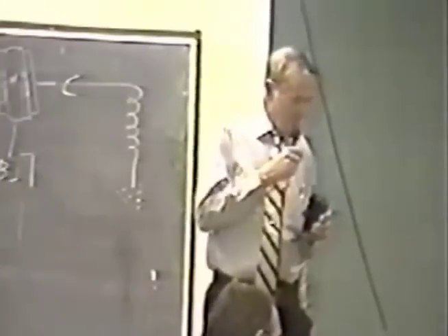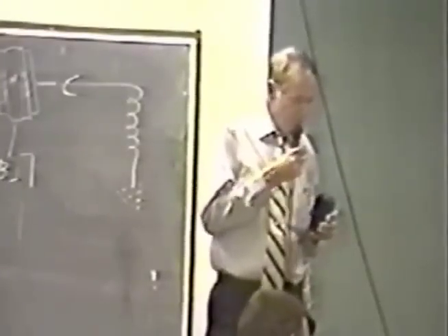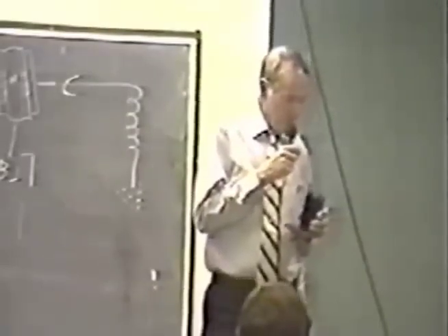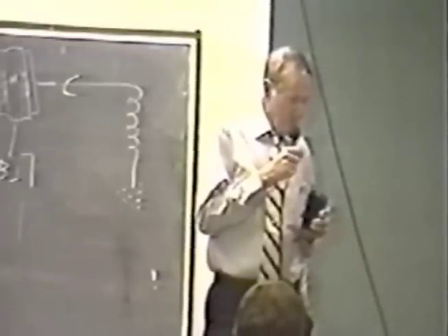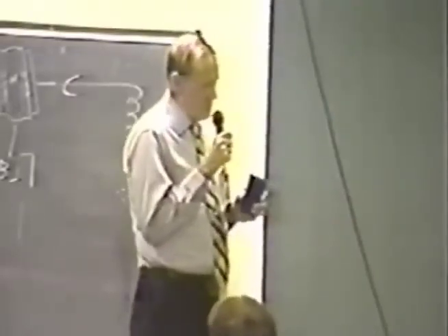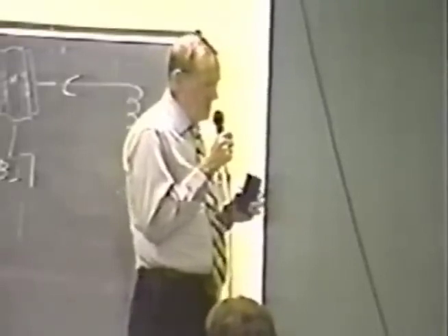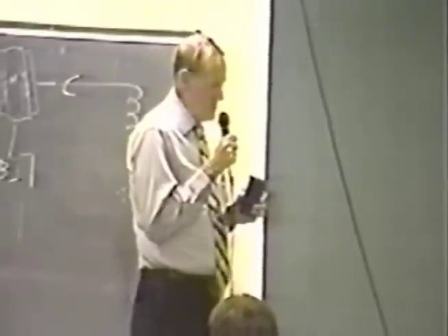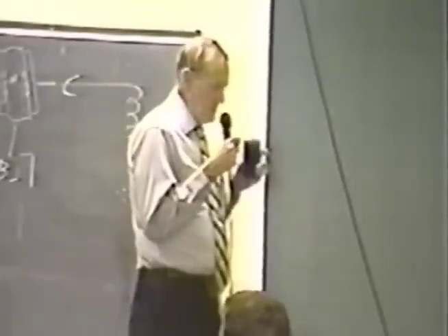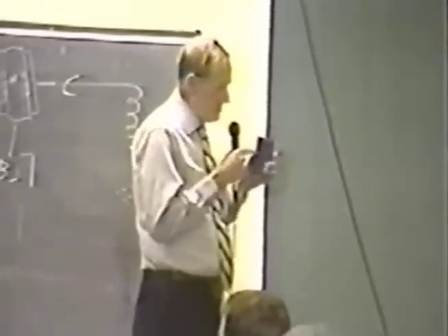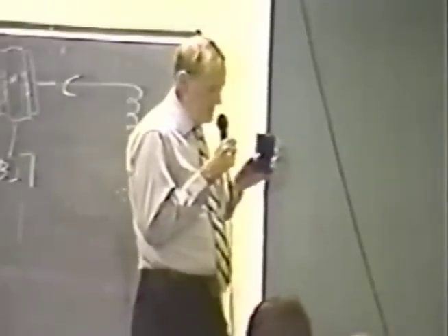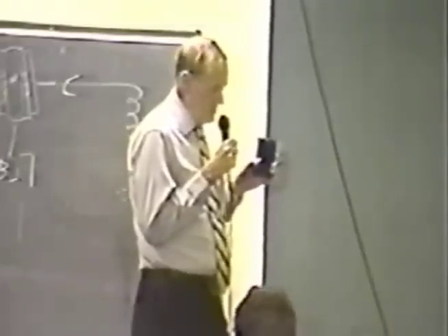You have a question? Okay. What are the possibilities of voice modulating the signal coming out, using it as a transmitting device, receiving communications? Very definite possibility, but one has to have a detector in order to demodulate, in order to use it as a useful transmission of intelligence device. You want to have 2 links, a transmitter and receiver. This is a transmitter only, and we do not have any modulating techniques on this. It is strictly a square wave generator driving it.